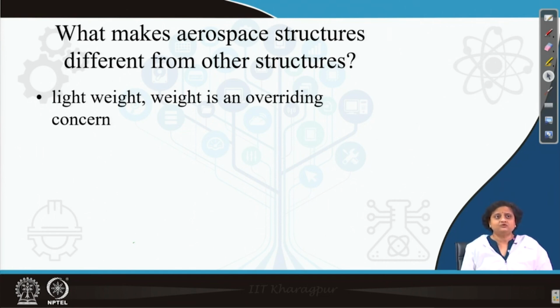Such weight constraint is not experienced in any civil or mechanical structure. Here in aircraft structure, higher weight does not only mean a higher amount of material involving higher cost, but higher weight also means higher fuel consumption, lower capability to carry commercial weight, and a higher cost of running this aircraft.